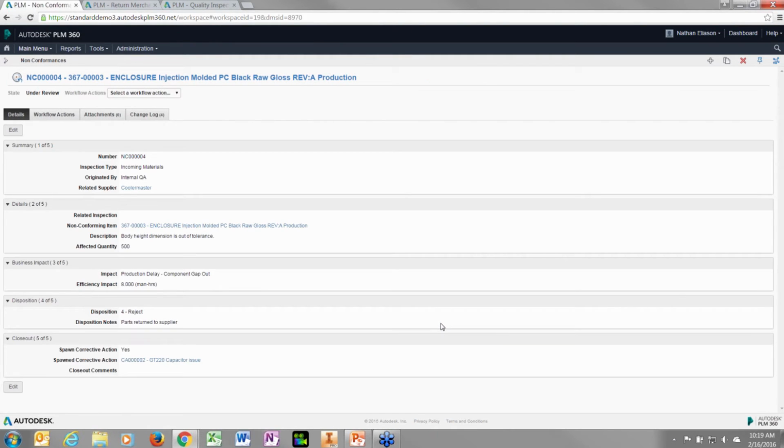So let's say that we did have 2 or more failures inside of our lot. The next decision we have to make is, what do we do about this lot that we determined is unacceptable? It might be that the issue that you've uncovered isn't so bad and you can still use the parts, so maybe we can use them as is. Maybe the out of spec is a problem, but there's a way that we can rework them. Maybe it's just a small number of them that failed, so we can quickly go through the dimensions that failed on all of the parts.